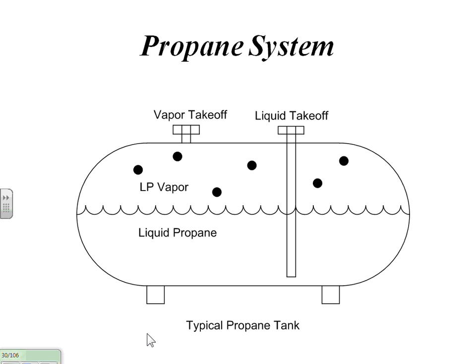They've got a primary loop with engine coolant running through a heat exchanger, and that heat from the engine coolant is enough to generate a vapor in the secondary. They run the liquid fuel through that side, and it vaporizes in that vaporizer. And then the vapor is fed into the engine. So it's basically still running on vapor, but it's a liquid takeoff.